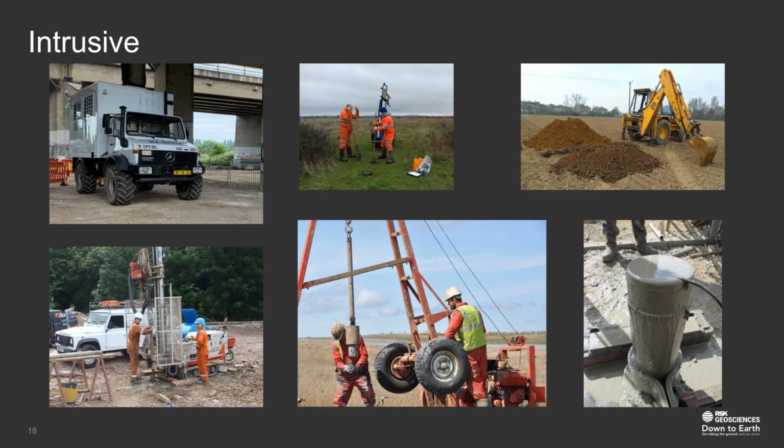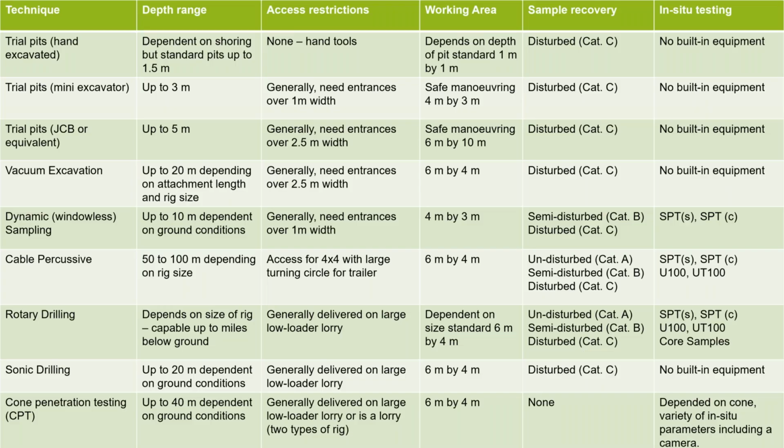This next slide, again, has quite a bit of information, but I've tried to provide you a comparison of some of the more common techniques that we use. As you can see, there's quite a variety of depth ranges, working areas, and sample recovery. This is why it's really important to consider your ground model and understand what depth you need to get to and what samples you need to recover, as this is going to really affect which technique you choose.